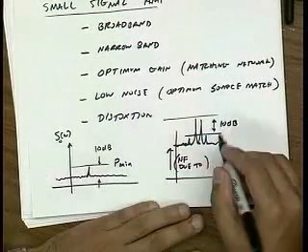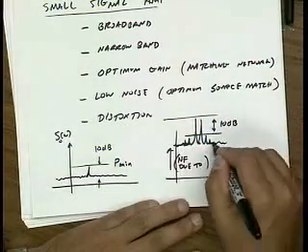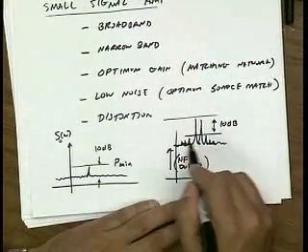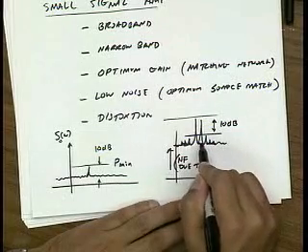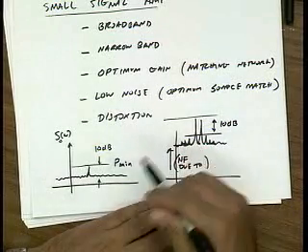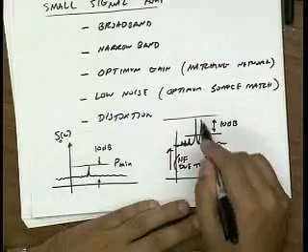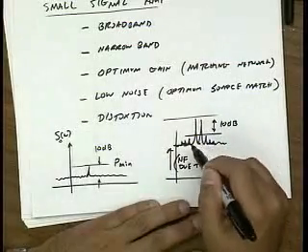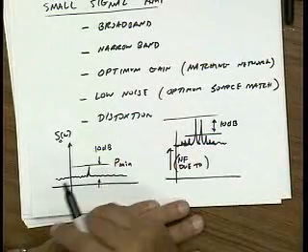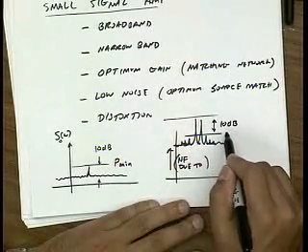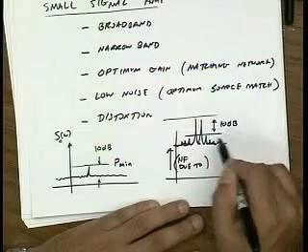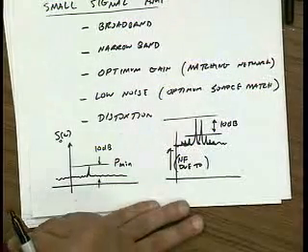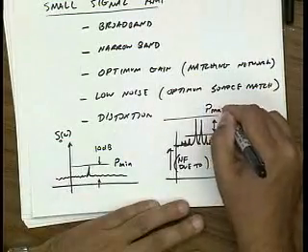Like these are the IM3 distortions, the IM5 distortions, the IM7 distortions. And these distortion products, for two tones that are very close to each other, all fall in band. You can think of a modulated signal as having an infinite number of tones. And so all this distortion is going to fall into your band and mess up your spectrum. So if you make the requirement that your signal has to be a factor of 10 bigger than these distortion products, like you did in this last homework assignment, this also tells you Pmax.